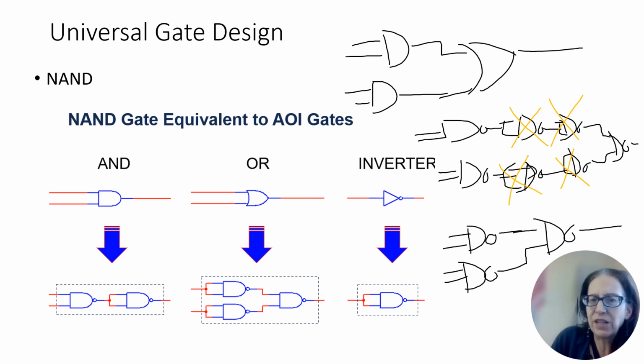And then the advantage to this is that now you only need one chip. The AND gates and the OR gates are in different chips, the LS04, 08, 00, whatever. And the NAND gates are all in one chip. So now you've gone from two chips down to one chip, and your circuit's going to do exactly the same thing. Is it more design work? Absolutely. Is there a payoff for it? Yep, there's a payoff for it as well.